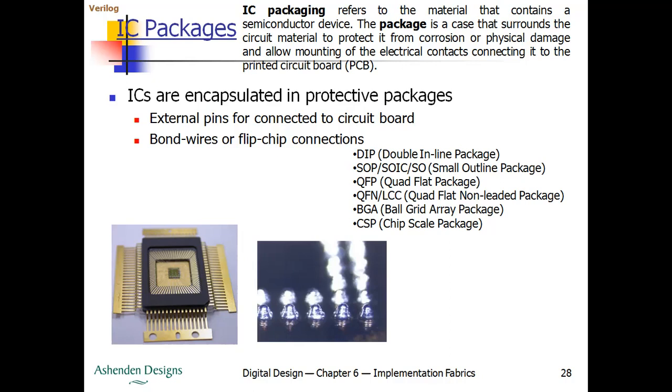The connection pads on the IC are covered in conductive material, forming the bumps, as you can see here. The IC is flipped over and fixed on the substrate of the package, and the bumps will be in direct contact with the substrate and the connection points.